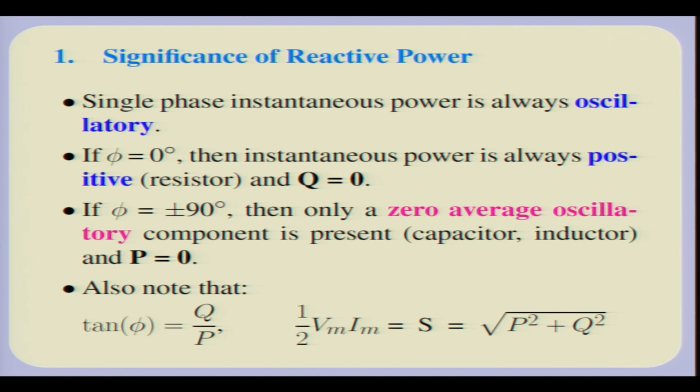Pay attention to what I said some time back, that if you have a circuit which draws reactive power, remember all these concepts make a lot of sense only for sinusoidal steady state circuits with linear components. So, please remember that somewhere in the back of your mind. Remember I mentioned that if you have non-zero reactive power, you are drawing more current than what is necessary to dissipate the amount of average power that you are dissipating. What it means is that if Q were to be 0, then you would draw lesser current, okay, for the same amount of dissipated power. So, remember these important things.